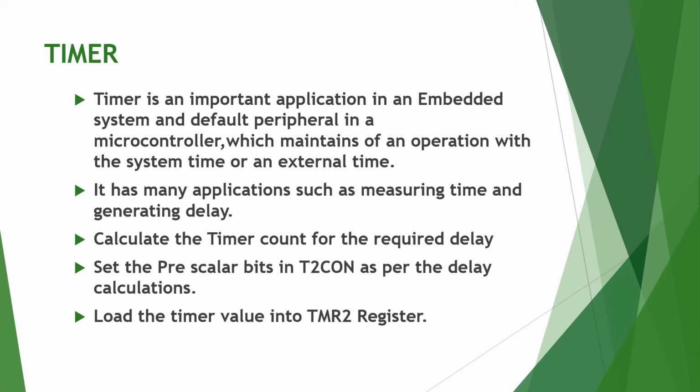Calculate the timer count for the required delay. Set the prescale bits in the T2CON register as per the delay calculations. Load the timer value into the TMR2 register.